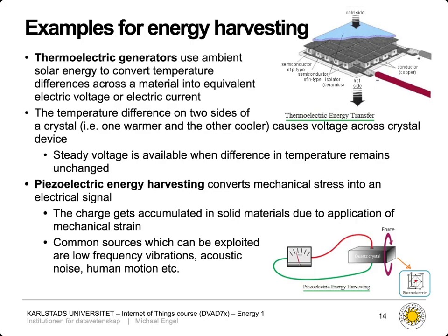A different way to harvest energy is piezoelectric energy harvesting. So this relies on mechanical stress of a component, so mechanical stress of a certain piece of equipment. And if we apply this mechanical strain to this component, we can also extract, using this piezoelectric effect, energy from this. This is the same effect that's used the other way around in clock generators for processors.